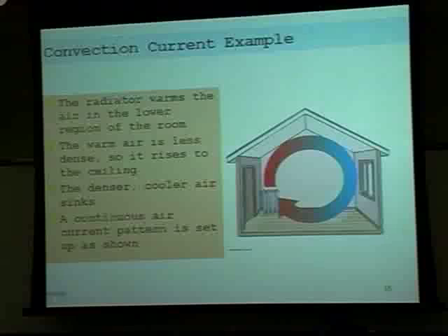In this case, would that convection be natural or forced? Natural. Actually, it would be natural convection after you got out of the radiator. It's due to the natural density difference of the air itself. You have no pumps, so it'd be natural convection.